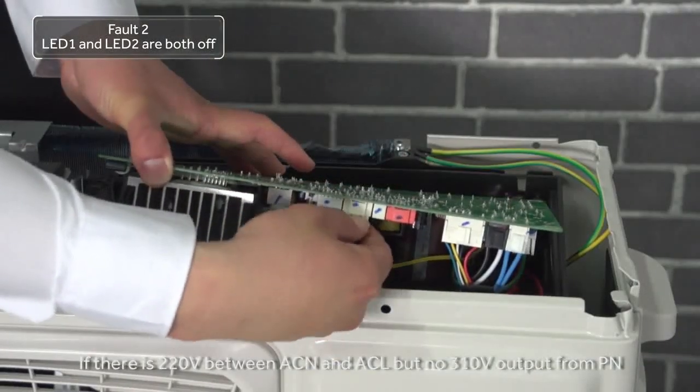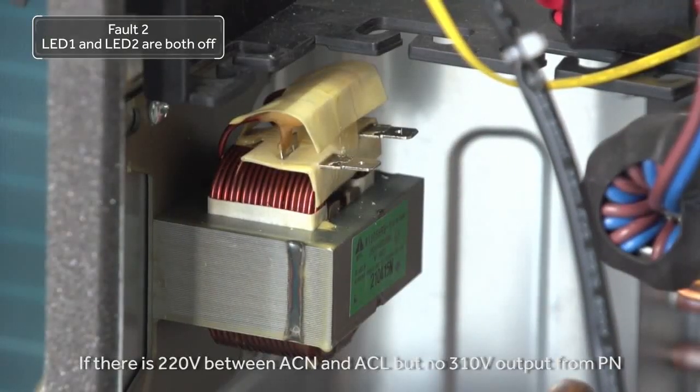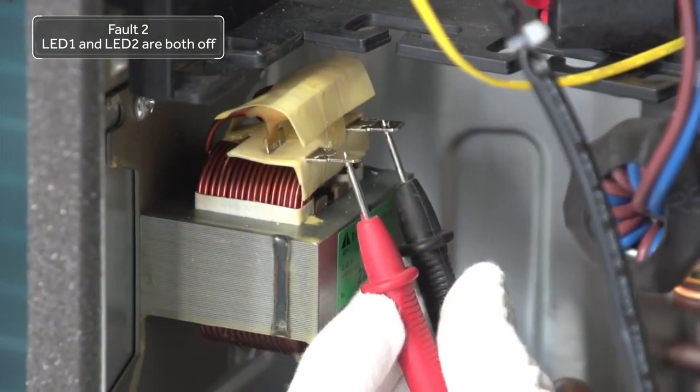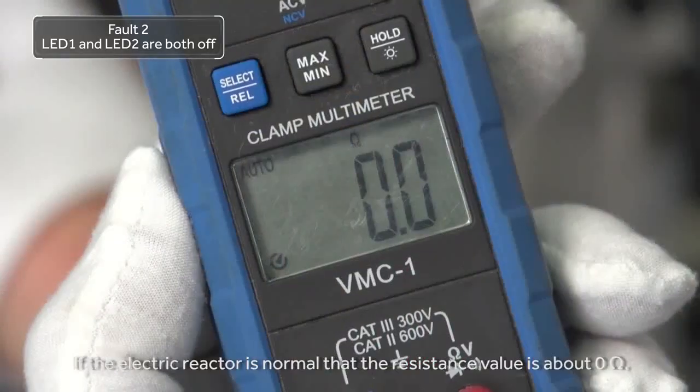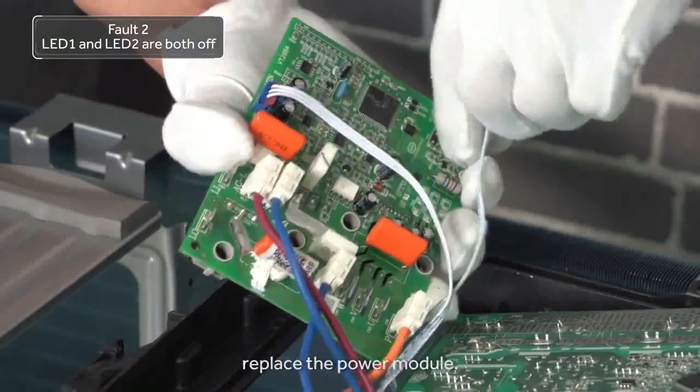If there is 220 volts between AC-N and AC-L, but no 310 volt output from PN, check the electric reactor. If the electric reactor is normal, that is, the resistance value is about 0 ohms, replace the power module.